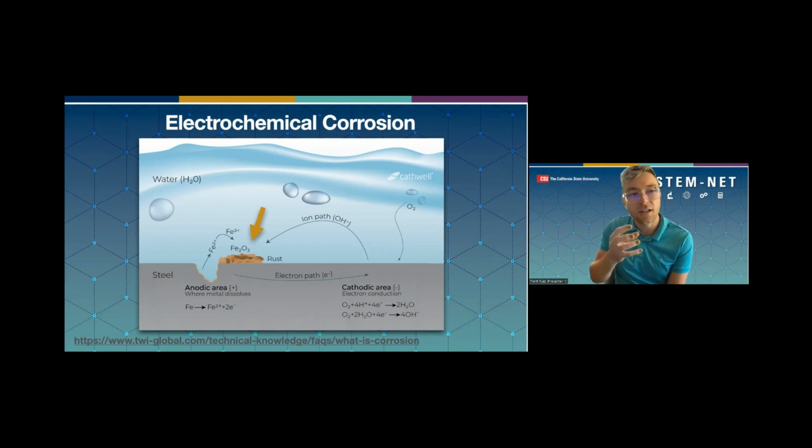The electrons that are flowing through the anodic regions then travel to the cathode, and once lost to the cathodic region, oxygen in the surrounding electrolyte reduces and reacts with the oxidized metal to produce metal oxide, commonly known as rust. And these electrochemical models work so well because of the insight that is gained in the proportional relationship to current density and oxidation. And so now we get to talk math, and it's one part I really like.